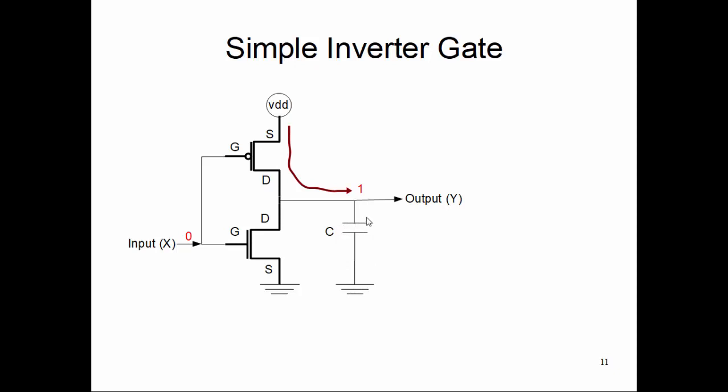Once it is fully charged, this electrical line stays at a high voltage, a voltage on state, which is logical 1. So as soon as we apply a 0 on this circuit, we see the capacitance get charged. It stores all the charge coming from the VDD side and keeps this line at logic high state, meaning a voltage on, because the capacitance is filled up.